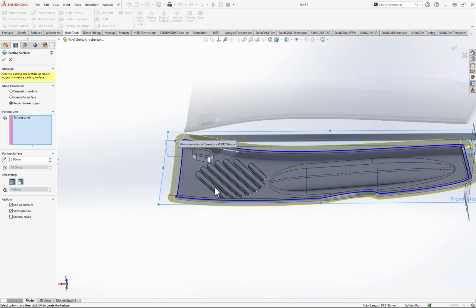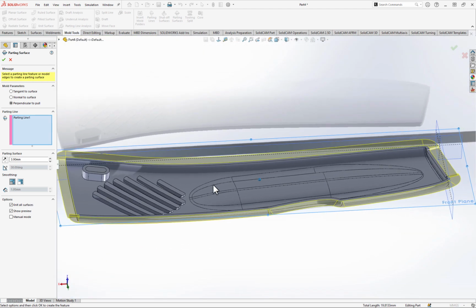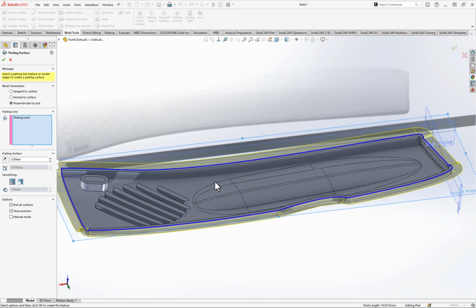And what this does is it looks at our parting line that we previously created, and it projects outwards away from that line a cutting tool, if you like, that will chop our mould into its upper section and its lower section. So those two sections are called the core and the cavity. The cavity is the one that has a kind of indentation in it, so material machined away, and then the core has material that sticks outwards.